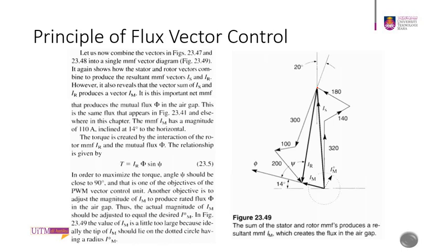IS we can measure and calculate. IR we can also measure based on IS, and in the result we can find the IM. So IM is the rotating magnetic field, and this will be referred to the speed of your motor. IM cannot be directly measured, so it needs to be calculated using the flux vector control.